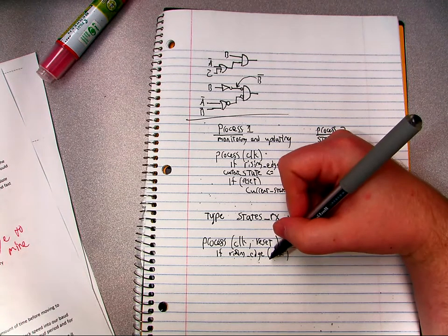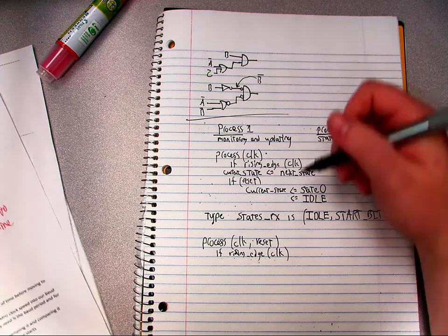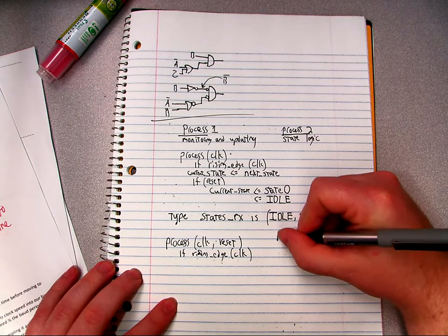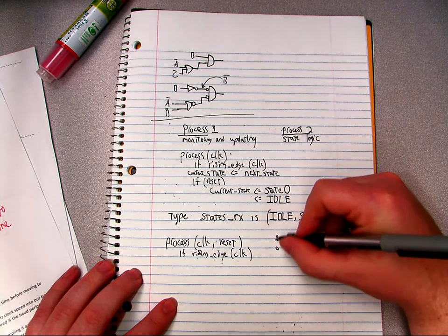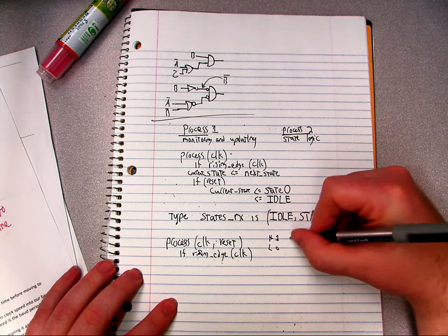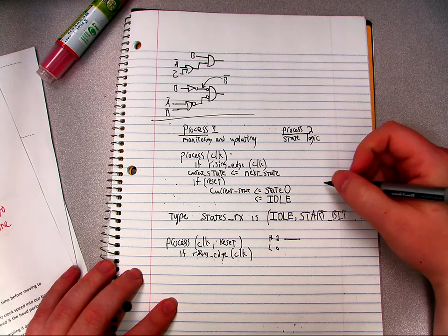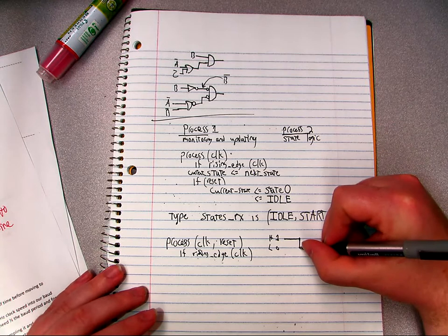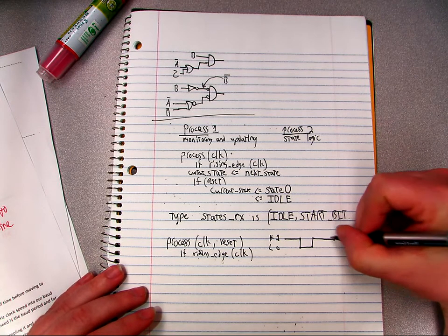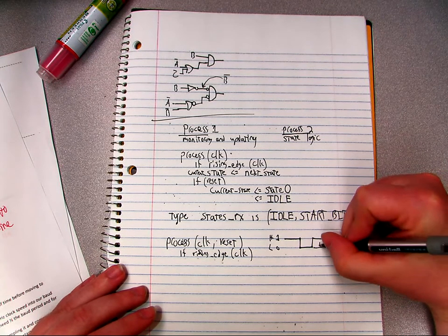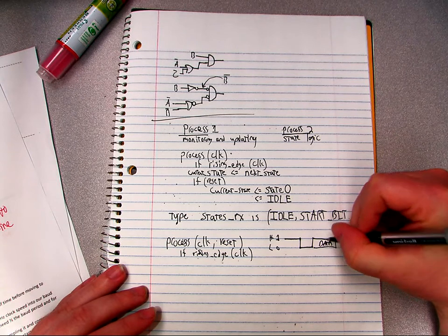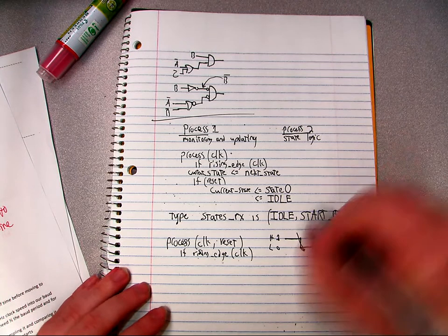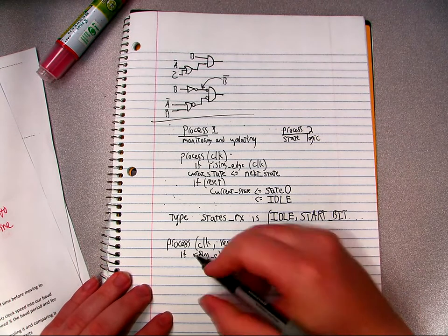And what are we going to do? Well, we know from what I talked about in lecture that if this is a 1, this is a 0 on the line, high, low, right? When it's idling, it sits at 1. So we know that's what it's going to do, and when it's about to start transmitting data, it drops to 0. So we're looking for this transition. But we know it started at 1.